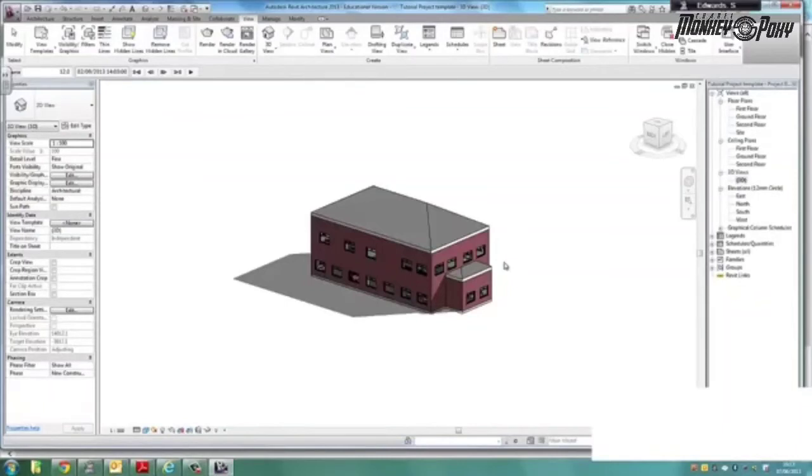It may also include the following types of information: a table of contents, also called a sheet list, drawing index, or sheet index, the project name and address, client's information, vicinity plan, zoning information, code compliance information, list of project team members, legal description of the property and its boundaries, and general notes.